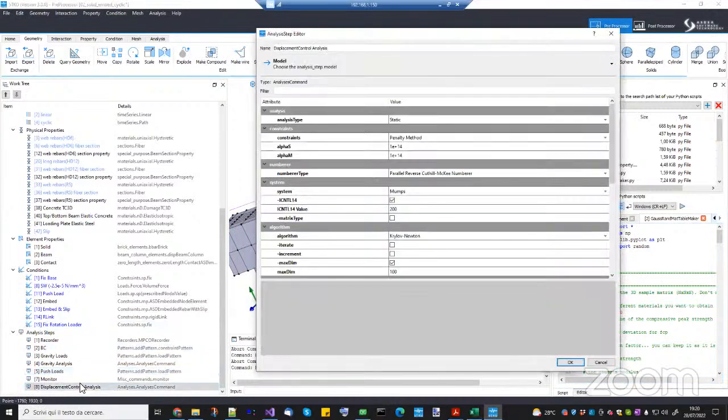Yeah. The normal spring stiffness that you put was, I think, very, very large. So you will have a negligible relative displacement between the steel plate and the end of the concrete beam. Exactly. You will not introduce some artificial pinching, right? Due to that, it will be negligible.